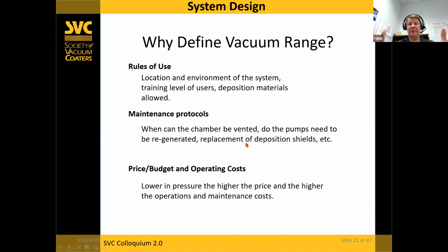Because the last thing you want to do is spend 2 or 3 days to pump a chamber down to a low base pressure, and then run your process and be forced to vent that chamber in order to replace material in an E-beam or change a crystal or do any kind of routine maintenance. It's just very impractical to say, I'm going to run my vacuum system for 4 hours, then I want to spend the next 4 days pumping it so that I can run it for another 4 hours. It makes very little sense. And that might be true or needed maybe 1 in a million times, but certainly it's not the rule and it's not very practical.